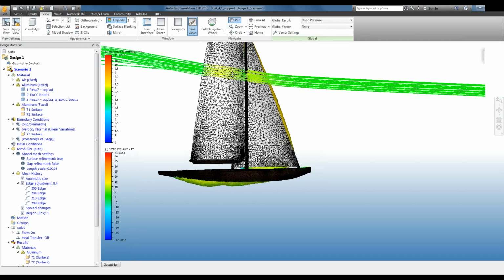Maybe I'd go to 1.05 to have a little bit more fineness in the larger sections of the sails. But truly, there's not a lot that is changing with the wind or the airflow at that point. Most of it actually is happening right at the luff or at the leech of the sail. So I'm not sure that actually would have given me any better accuracy. But it just might have been something to try while I'm saying, yes, I really want to benchmark this to the best accuracy I can have. Now, if you were going to try and actually separate flow in this area, you're going to need a finer mesh, but to separate flow, you're going to have geometry that would have stimulated that. So your geometry would have driven your mesh there. I hope that answers everybody's question.